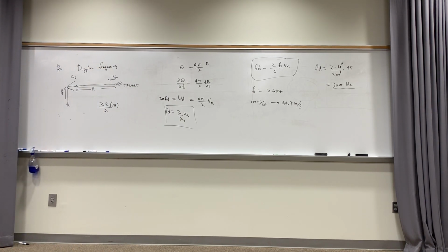Well, you remember, did you have heterodyning? Suppose you had a signal coming back at you, like a 10 gigahertz signal. You could represent it as cosine of 2 pi times 10 to the 10th t plus some phase angle. But suppose that it's also being modulated in its amplitude. Suppose it's got an A of t times that cosine of 2 pi times 10 gigahertz t plus a phase angle. And we want to recover just the amplitude.